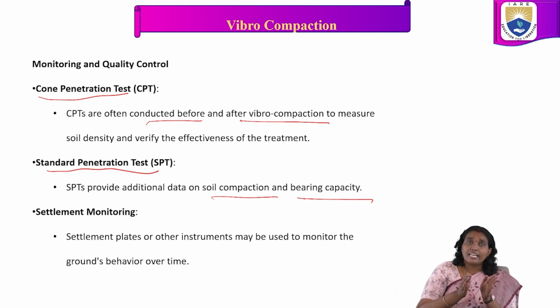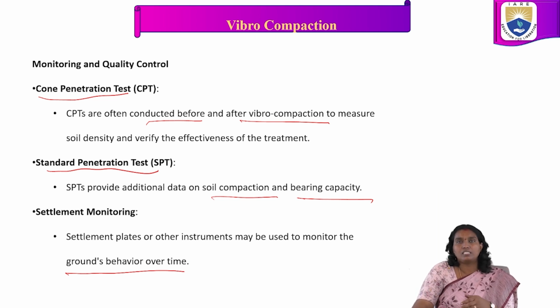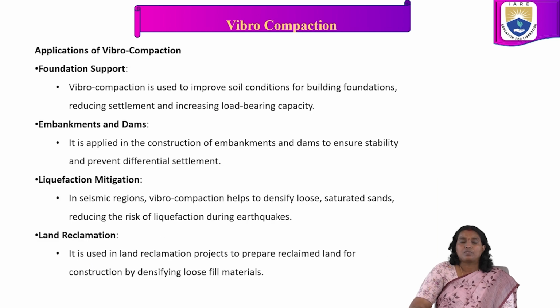Now, settlement monitoring. Settlement plates or other instruments may be used to monitor the ground behavior over time. So, once the vibro compaction technique is done, we have to monitor to understand the ground's behavior over time.